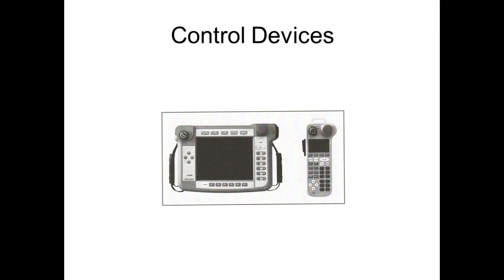So if I've got an accurate 3D model of my work cell, we can literally go over to this robot. We can take a program on that robot. We can download it into a compact flash card. We can bring it over here, upload it into the simulation. The robot over there is still running like crazy. We can make modifications over here, and we can take it over there and upload it. And the robot was basically out of production maybe 5 minutes.